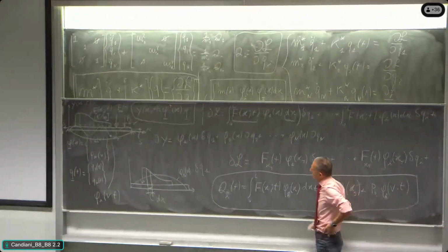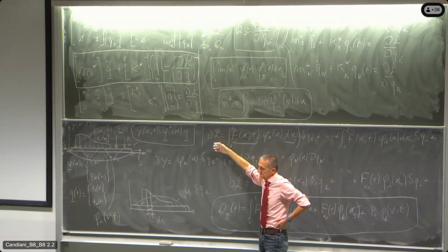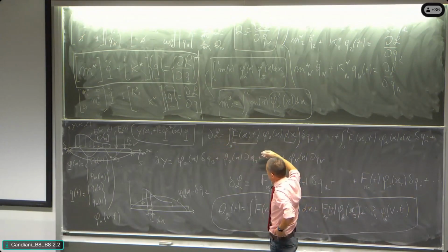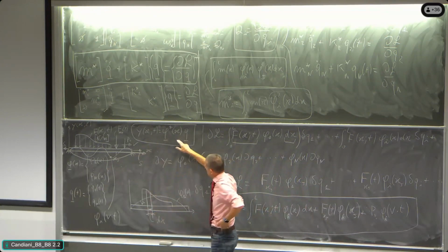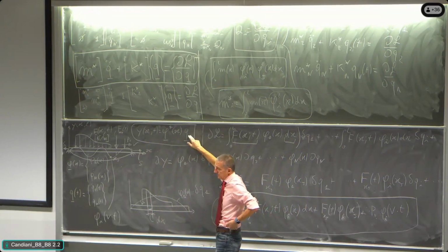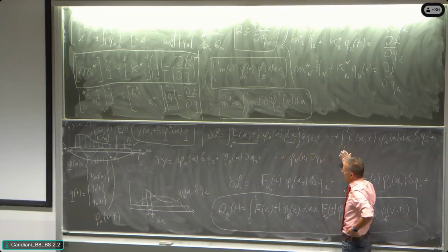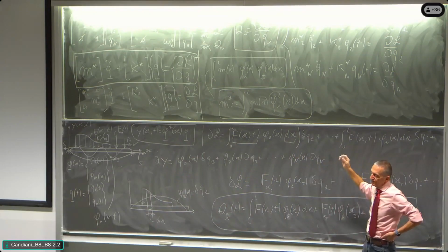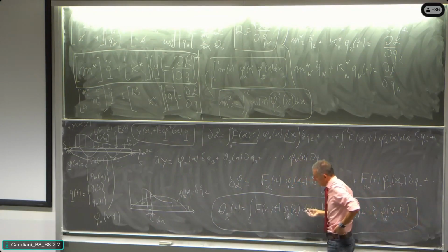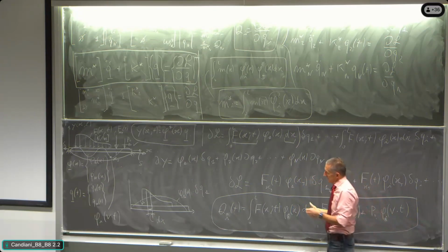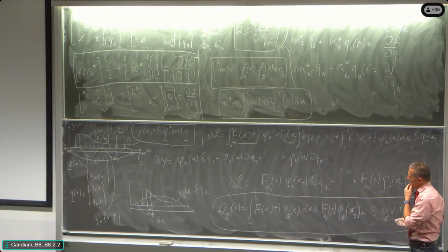But generally speaking, what we have to say in a very general way is to write the work of the external forces as an effect of the distribution of displacement depending on the representation of the dynamics of the system in terms of principal coordinates, and to write the virtual work as the work of the distribution of external forces associated to an infinitesimal virtual displacement that is coherent with the constraints and that is associated to infinitesimal variation of each principal coordinate itself.